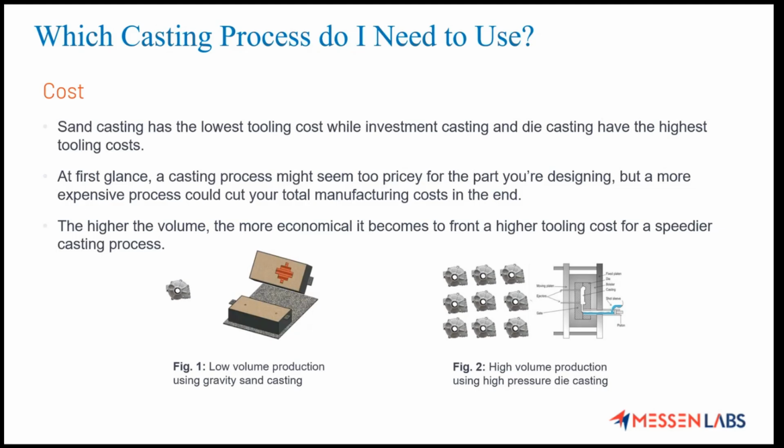While investment or other die castings have high tooling cost, where you require high pressure or low pressure pumps to pour the molten metal into the cavity. At first glance, a casting process might seem too pricey for the part you are designing, but a more expensive process could cut your total manufacturing costs in the end. The higher the volume, the more economical it becomes to front a high tooling cost for speedier casting processes.